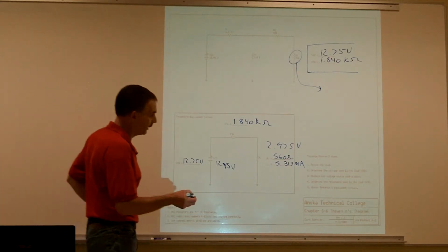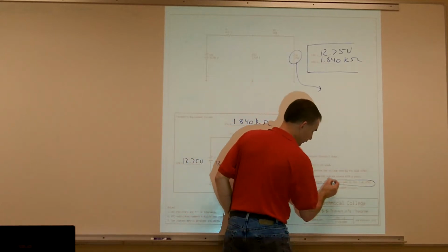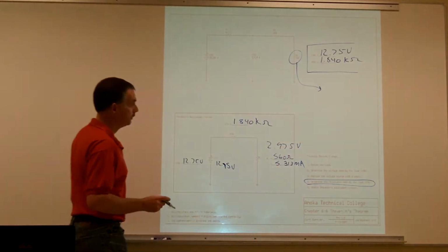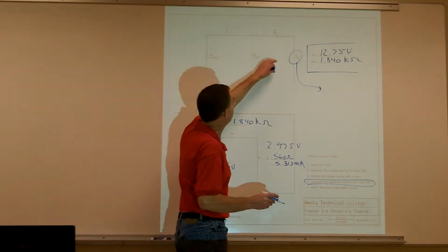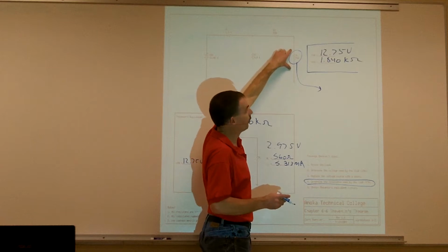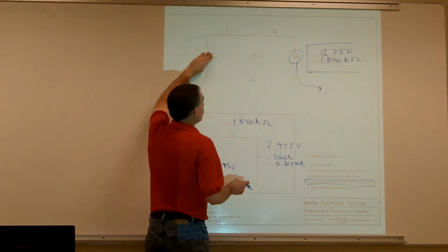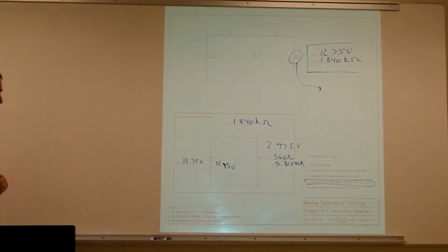I think the biggest one here is determining the resistance by the load. That's where we replace that with the voltmeter. Remember, and just replace it with an ohm meter. Treat your ohm meter as the power supply. Short this one out, and then redo your circuit. If you remake your equivalent circuits, it becomes a little bit easier.